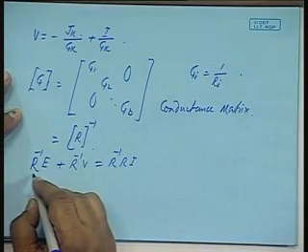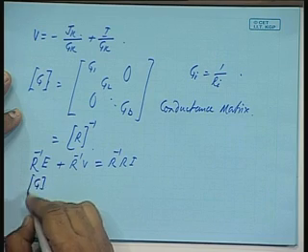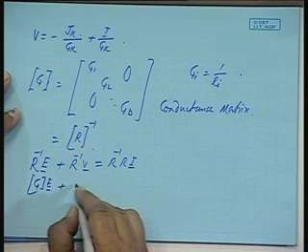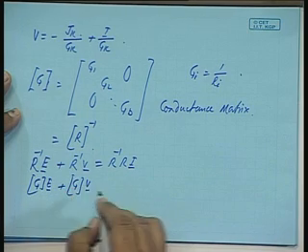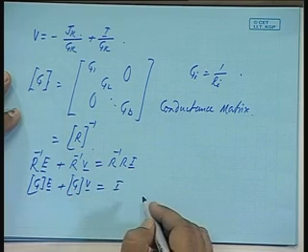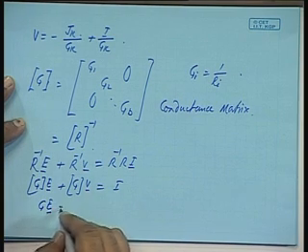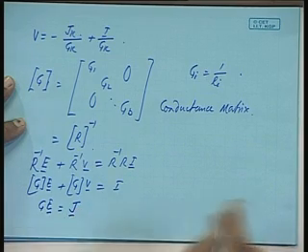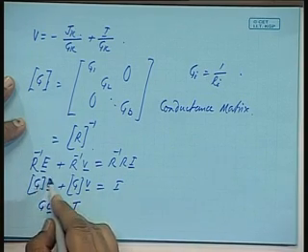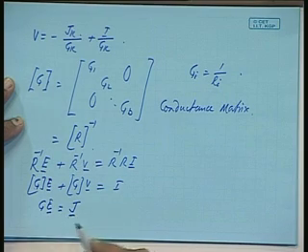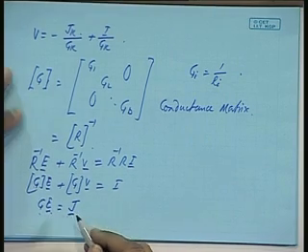So, R inverse E is nothing but G into E, they are all vectors, plus G into V is equal to I, okay, or G into E is equal to J. Taking the source voltages only, the equivalent source current vector J will be G into E equal to J.